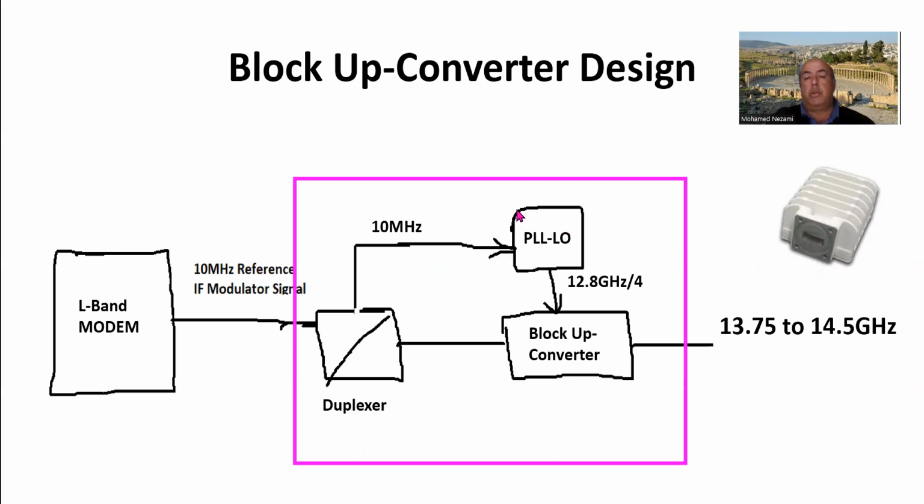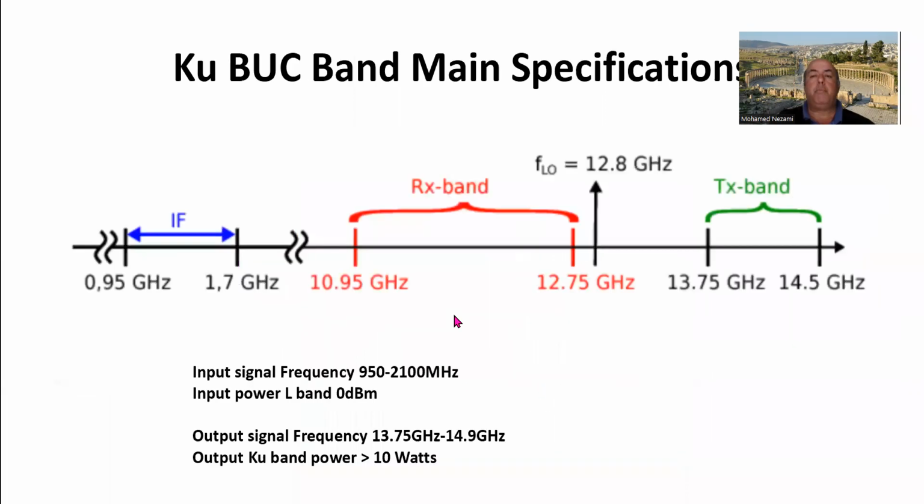The reason we do this is because there are plenty of S-band synthesizer chips that we can use from TI, Texas Instruments, or from Analog Devices. So we use these to generate the signal, and then it's at 1/4 of the frequency. Usually the local oscillator for this band is 12.8 gigahertz. So we divide that by 4, it's 3.2. And then in the up converter itself, we multiply it by 4 to generate 4 times that frequency, okay?